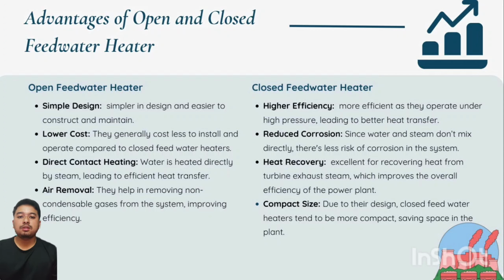This is important because non-condensable gases can reduce the efficiency of heat transfer and cause corrosion in the system. Now let's look at the advantages of closed-feed water heaters. First, higher efficiency. Closed-feed water heaters operate at higher pressures, which enhance the heat transfer process. This results in better overall efficiency for the power plant as more heat energy is captured and utilized.